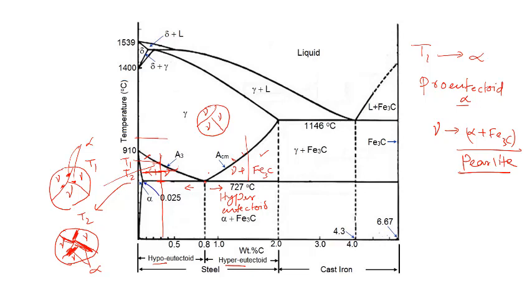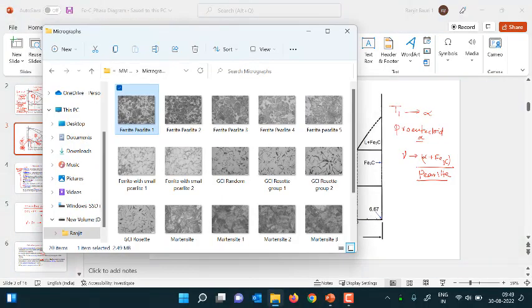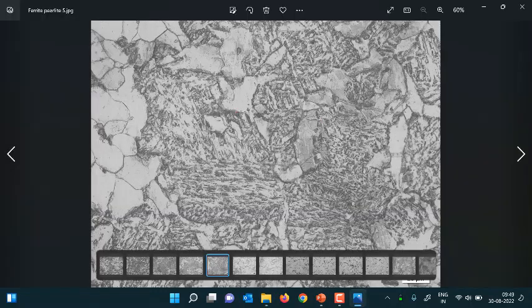Okay. So, if you look at the eutectoid microstructure, then it would appear like this, completely pearlitic. So, let me see if I have a fully pearlitic microstructure, maybe not. Yeah, but anyway, these white regions that you see, those will not be there. It will only be these black grains containing these lamellae appearing all over the microstructure. Okay. So, it will be 100% pearlite.